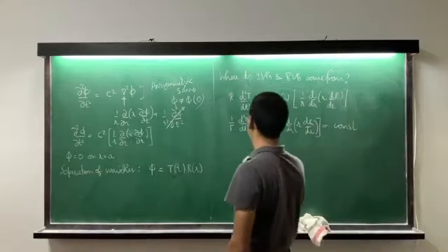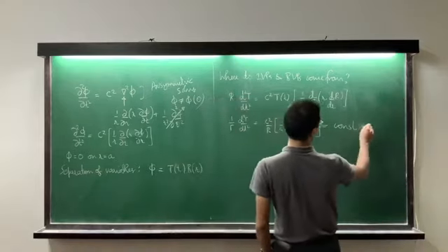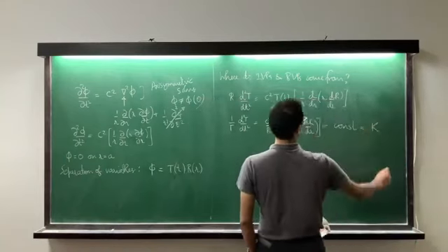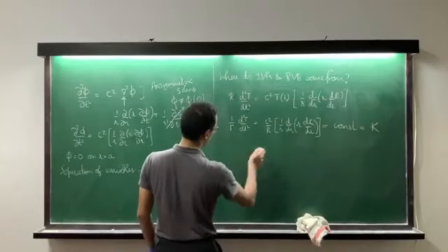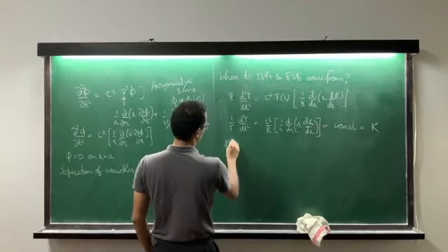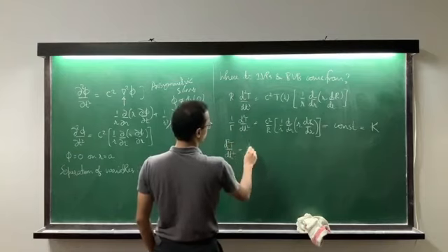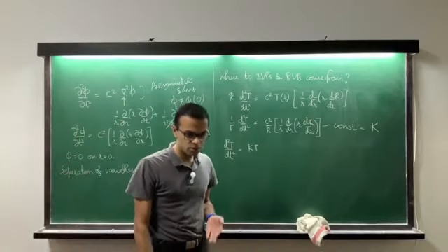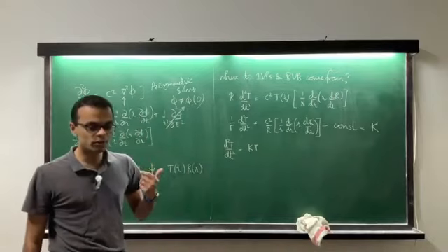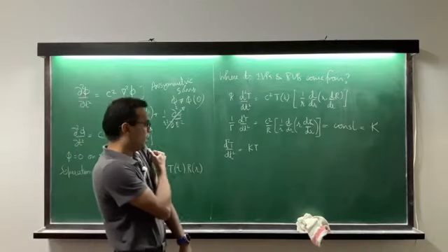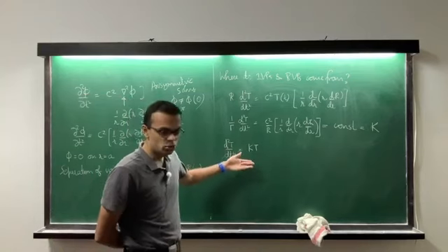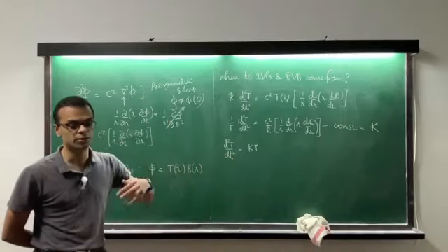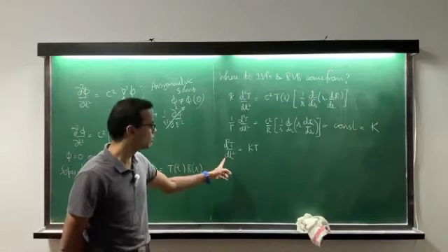So you can open this up one by one. You have now two equations. Let's say the constant is some k. So I look for first the capital T equation, that is d²T/dt² is equal to k times T. Now remember, I'm looking for vibration solutions, so presumably I'm looking for solutions that look like sin ωt, cos ωt. I have an equation that looks like that, but then I have this k. If k is positive, then I'll get only exponentially decaying or exponentially growing solutions, which is not what I want. Second order ODE, constant coefficients, we've seen this before.